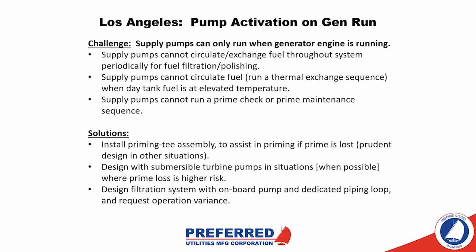We want to circulate that fuel with the bulk storage tank oil in order to cool down the fuel in that particular day tank. We can't do that unless the generator is running. Thankfully, in a lot of cases, the generator is running when this is going on, so that may in fact be possible even while the generator is running.